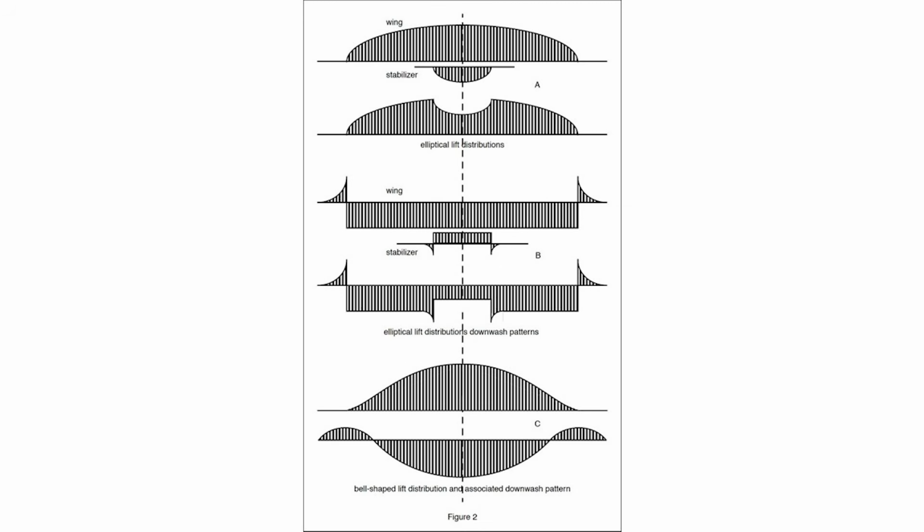With the bell-shaped distribution, the vortices are purposely located inside the span rather than at the tips, and this causes the tip to experience an upwash, which then causes the wing to have an induced thrust at the tip, as the airfoil resultant vector is leaned forward. Like we just reviewed with the elliptical distribution, you strive for an even downwash behind the wing, but here, this downwash becomes upwash at a point somewhere around 70% semi-span.